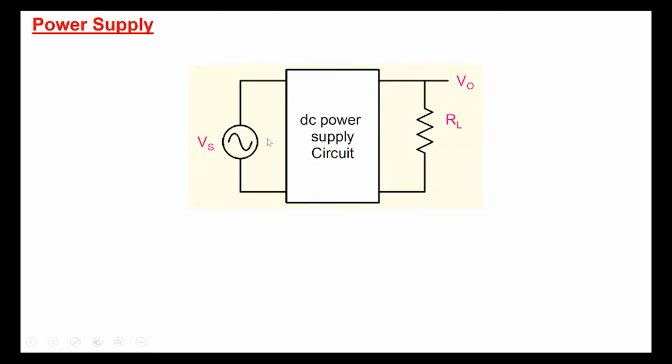So, as just mentioned, the input is an AC signal that we get in our homes, and that's 220 volts RMS, and the peak value is then 220 volts multiplied by square root of 2, which is 311.127 volts, and the frequency is 50 hertz. Let's say for some application we would require a voltage of 12 volts.